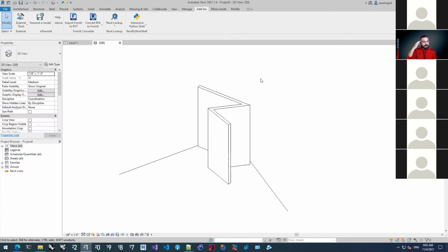Think about there being a table inside the Revit document that says, these are the walls table, right? And this table is like an Excel spreadsheet, and it has certain properties that are specific to walls. It doesn't have anything that's extra. And inside that table, there's a line for every wall that you have created in your Revit model, right? And when you schedule the walls, that represents the information inside your database, right? And you get to see what properties and whatnot are available to you.